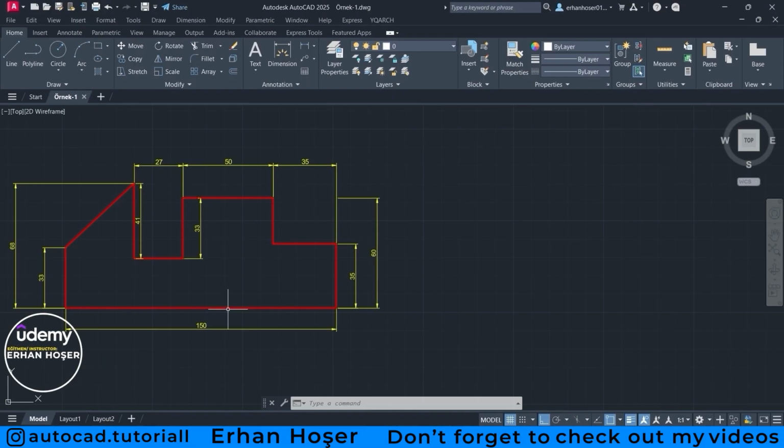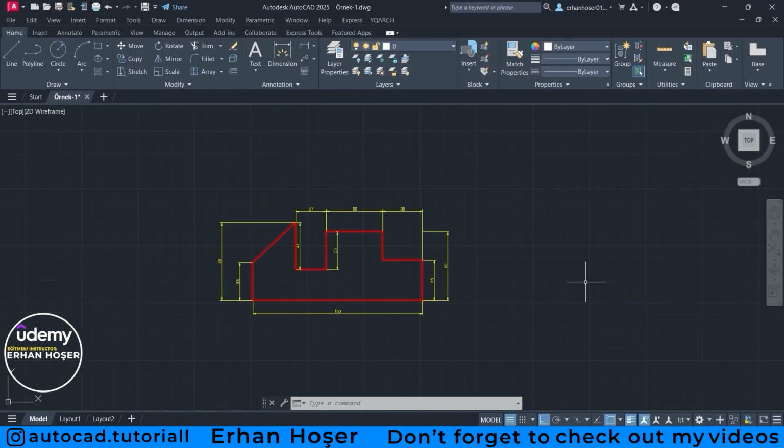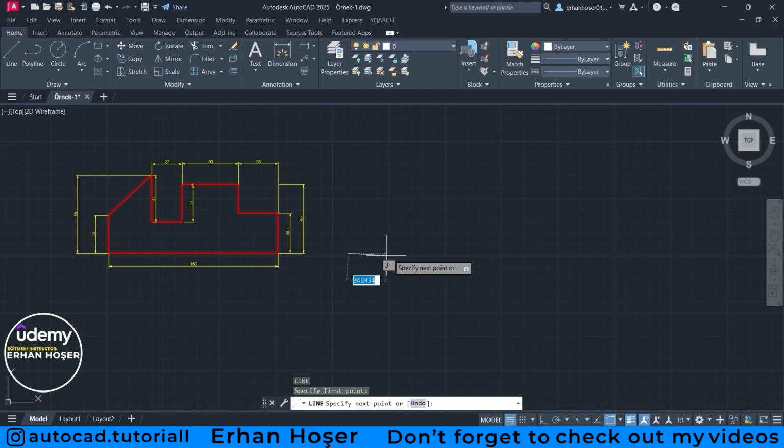At the bottom left, from this point to the right side, a measurement of 150 units is given up to here. I pressed L, I pressed space, I clicked once on any point. When I move my mouse, I press F8 so that we can draw straight. I moved it to the right side, entered 150 on my keyboard, and pressed enter.